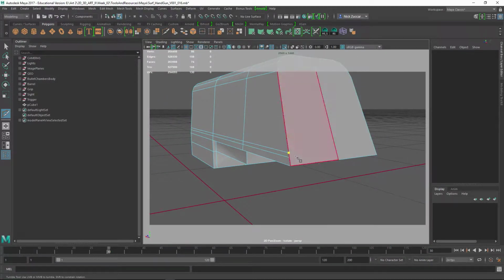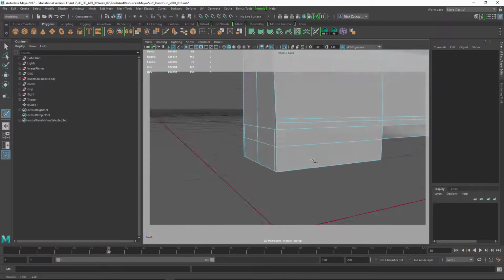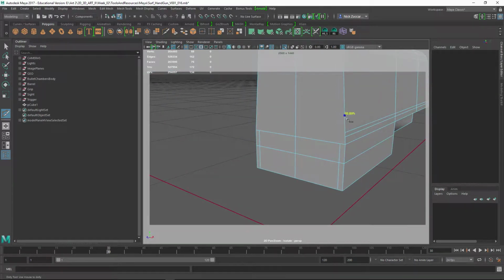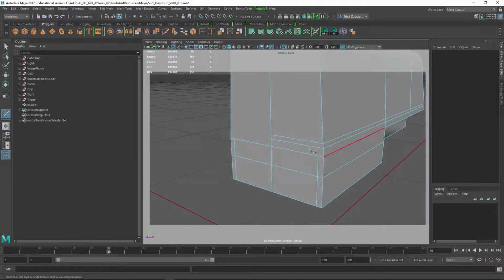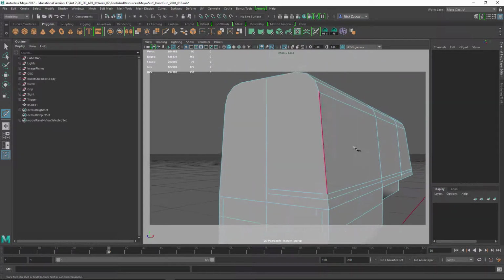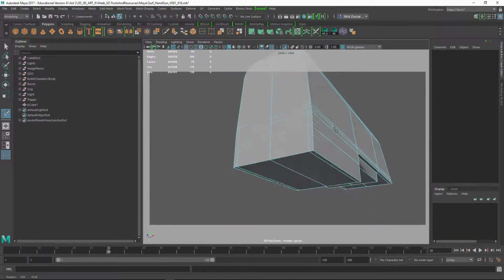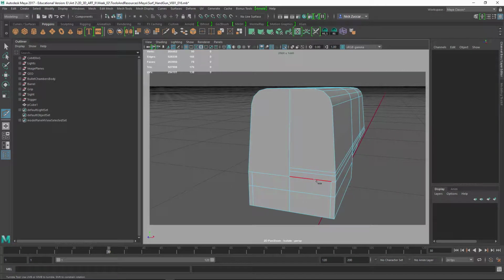Let's take these lines all the way across, hold down control and shift, and it should give us that 90-degree angle, which comes in pretty handy. Take a look at the front of this. Let's do the same thing here. Go across, hit enter. Go here, hold down control shift, hit enter for that. And since we've already got this edge that's already built up and through here like this, I'm going to continue it up and through here for now.